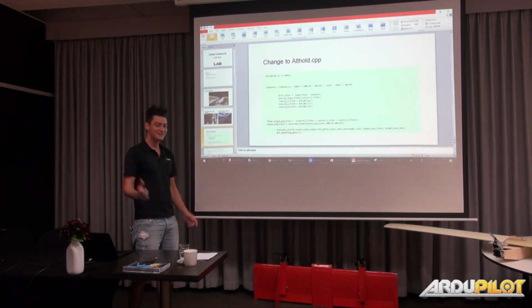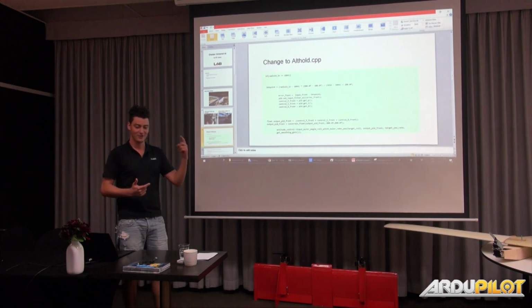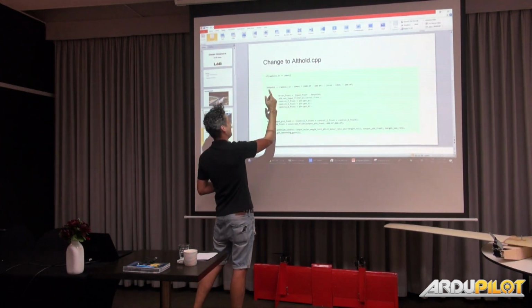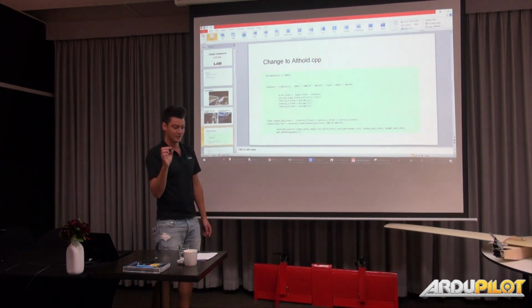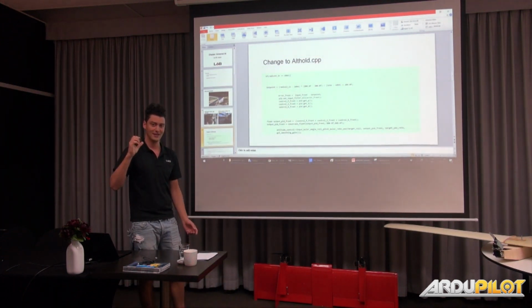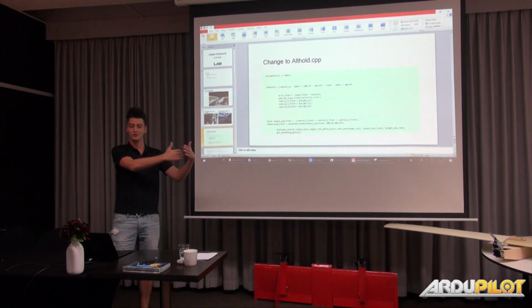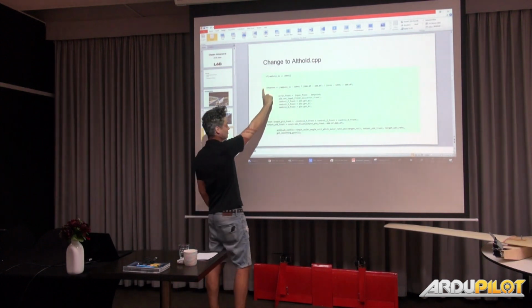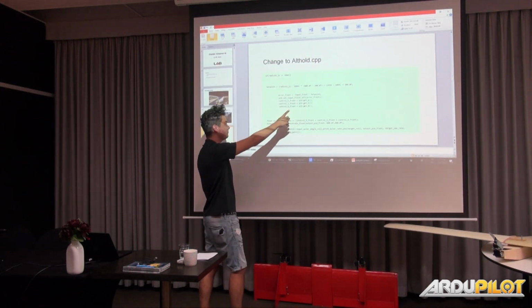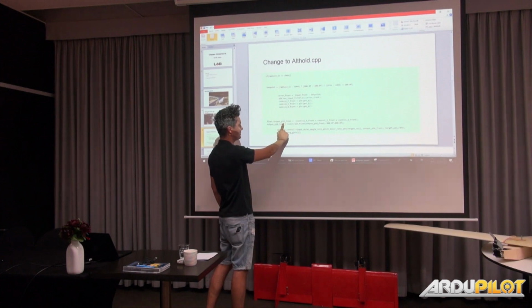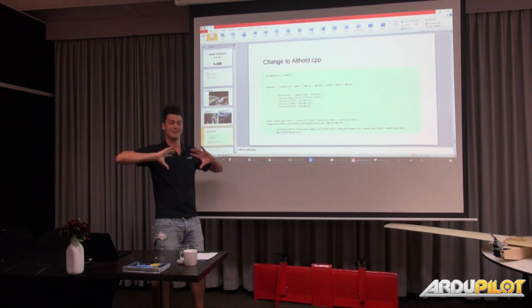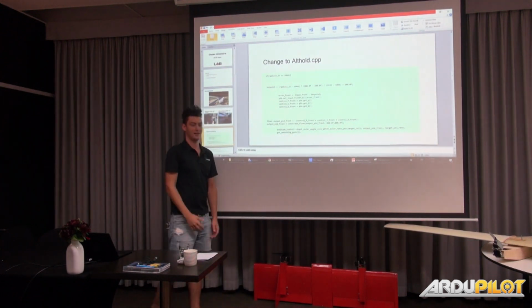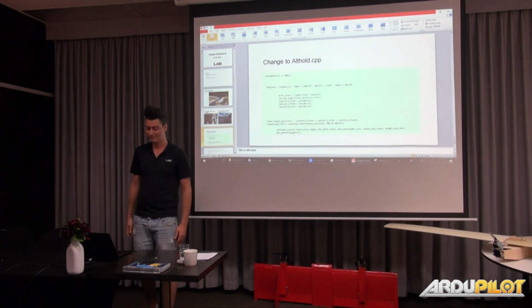As a safety, I have a switch that you turn on, and it gets you to another alt mode. And in this one, I have a set point which you can control with an up. Like the user wants to keep the drone 2 meters, 8 meters, so he can turn the drone. And then that set point goes to a PID loop, and then you get the output. I constrain it so I don't have a very difficult angle. And then I give it to the attitude control, and the drone does the job.